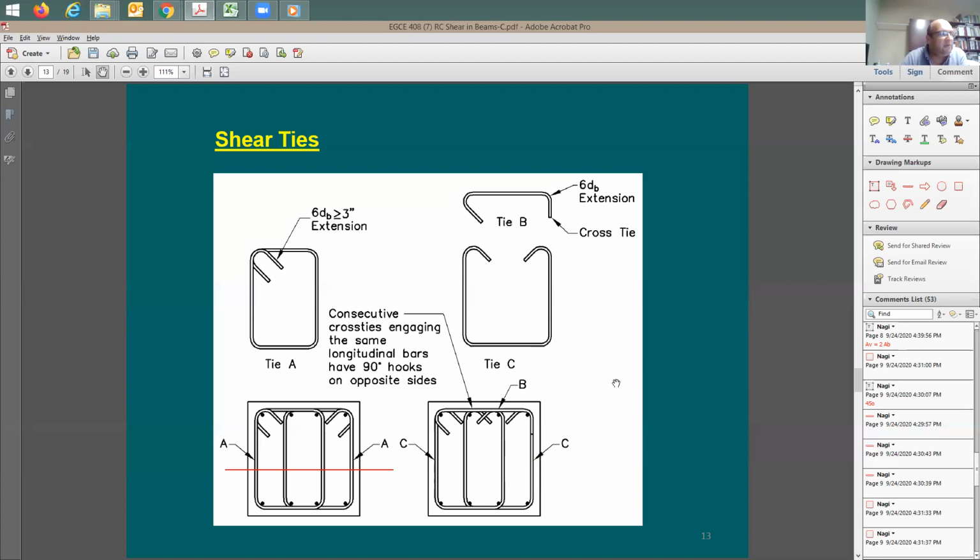If you like to start, I'm sure that you like to start only with 2 legs, right? Why would you put multiple legs? Because it's going to be taking time from the people working in the field. So you would like to reduce the number of these legs. So maybe you'd like to start with number 4 ties. I'm going to say usually start with number 4 ties.